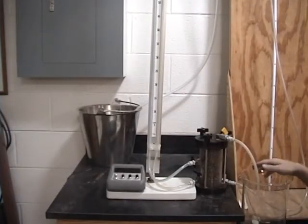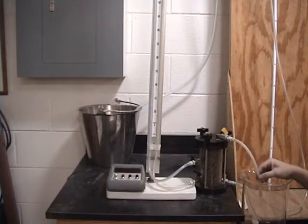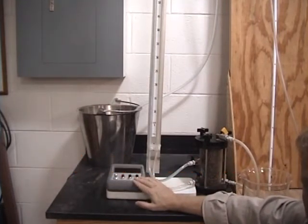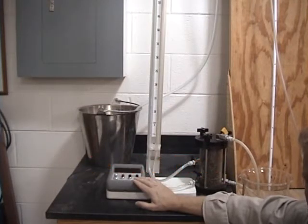Here I've also added some large graduated vessel. We're going to want to measure and quantify the flow volume, and we have some timing device, and we're going to measure the time. So we're going to come up with a flow rate, lowercase q, which is flow volume per unit time.